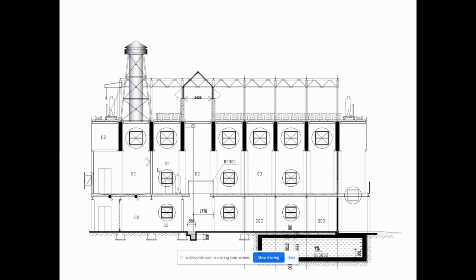it's not on the drawing, but it's an absorption chiller. I got the wrong name at first. An absorption chiller is like a reverse refrigerator actually, but it works with hot water, and it can produce cold water at about 12 degrees centigrade, which is then pumped into the insulated tank at the bottom of the building in the basement, as a thermal store. And then we can pump that cold water to cool down the beams that are formed